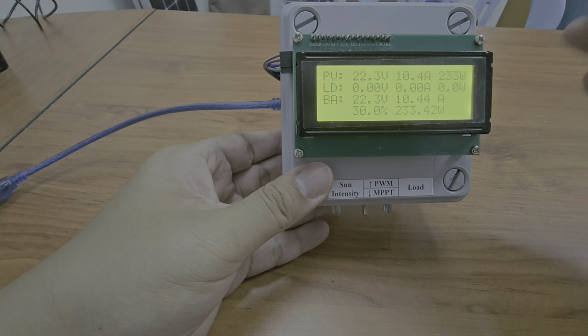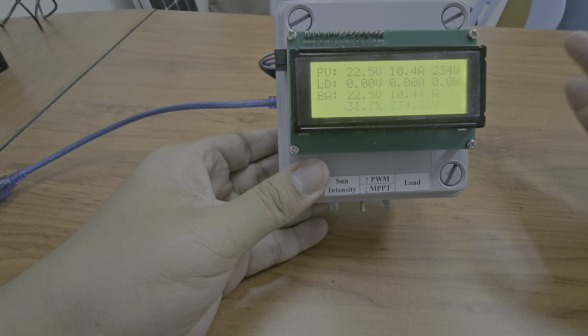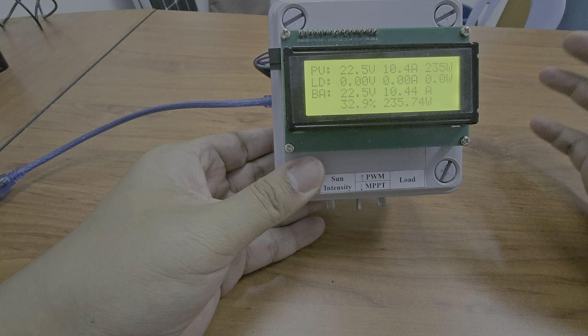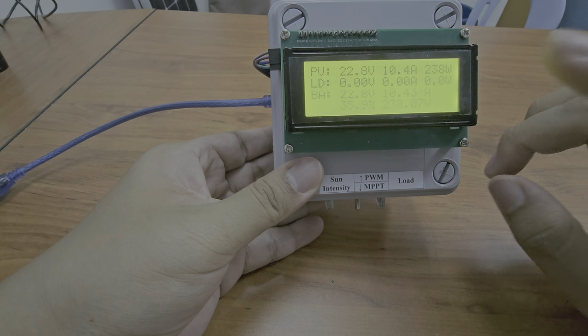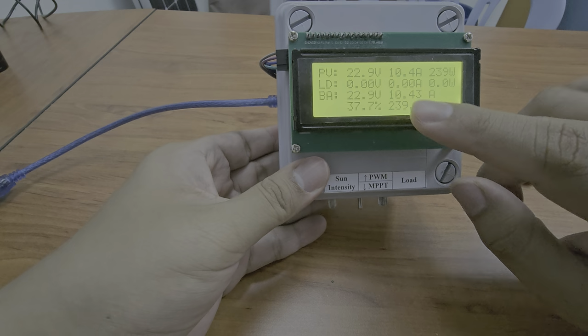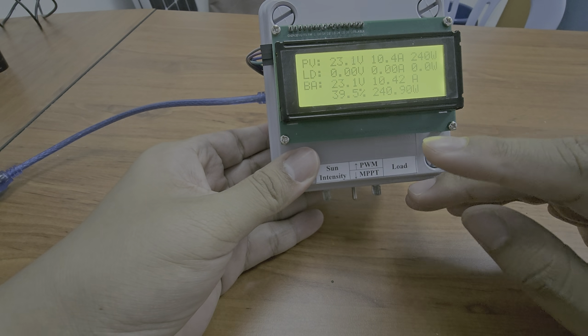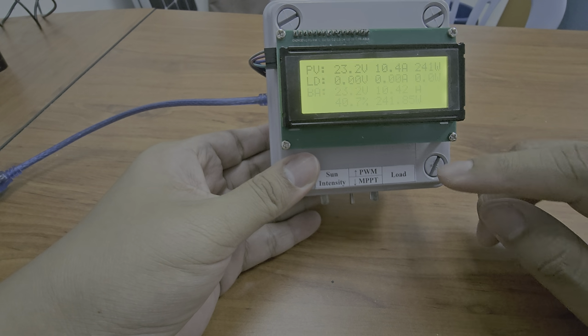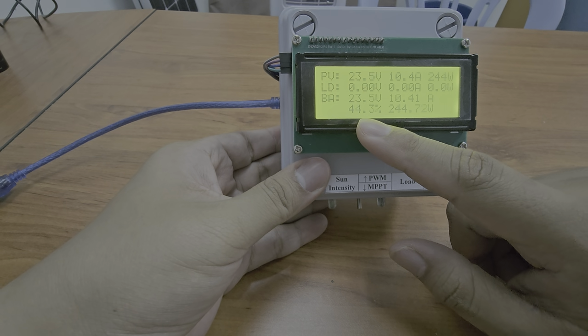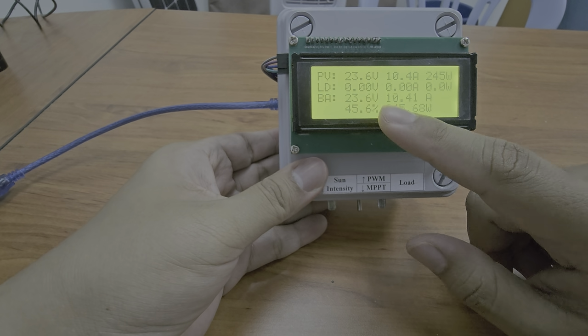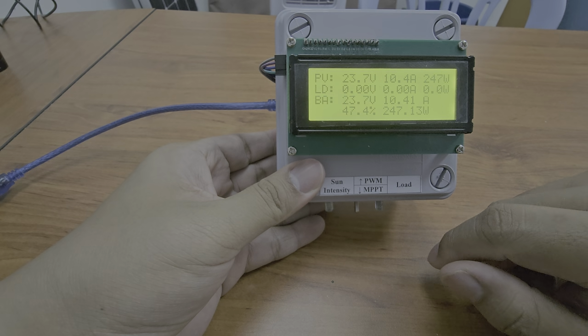Why don't we connect and disconnect, connect and disconnect the load? Basically it can damage your load. For PV it is okay, but for the load you cannot do that. So you have to set some reconnect voltage for this one, but for this case this is reconnect SOC. I set it to 50%. So you can see here after 50% it reconnects back.